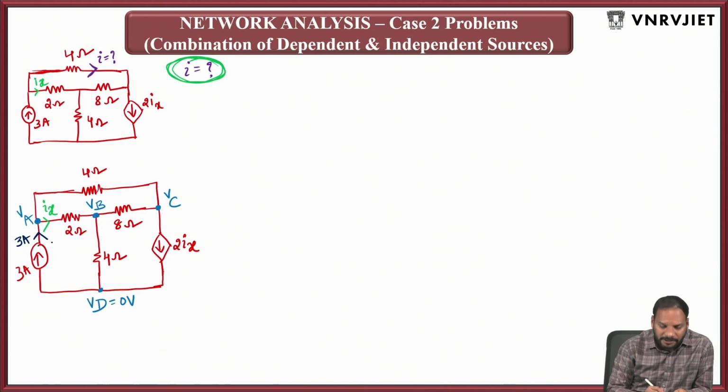Okay, this branch is fixed. And coming to this 2 ohms, already Ix is the branch current. Now, why take the headache of keeping one more current there? It is not required, right? So try to keep that Ix as it is, and let us continue the problem with the same branch current, Ix. Now, taking here one more branch current, that is I1.